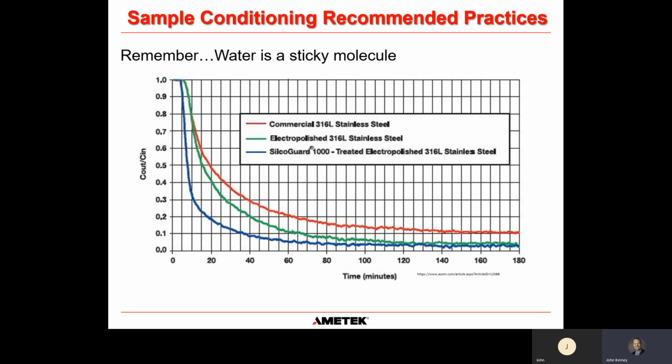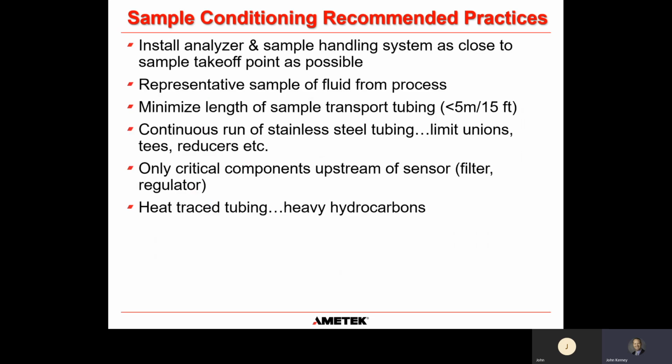So it's a real challenge for us to understand and make sure that we have a proper sample conditioning system to avoid the issue of water stickiness and water absorption, which all relates back to the hydrogen bonding and the polarity that we talked about at the beginning of the presentation. And then last thing, just a few recommended best practices from me on sample conditioning design with respect to moisture measurement.